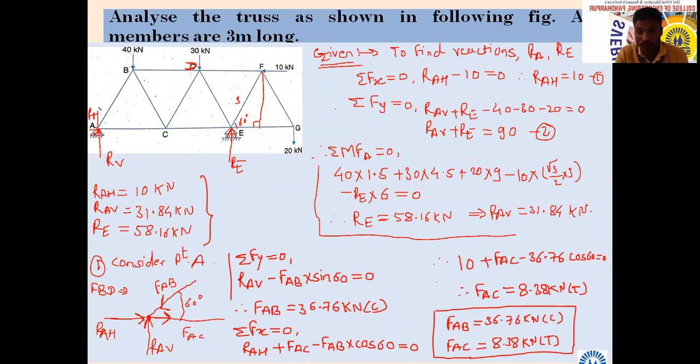So apply the logic. Likewise, you have to think during your examination. You should not blindly select any joint or any problem while solving engineering mechanics. Blindly, without thinking. So if we go to joint G, how many unknowns are there at that point? How many members are there? 3. How many unknowns am I asking? 2 forces. 2 unknowns are there. We can solve that. Is it correct?